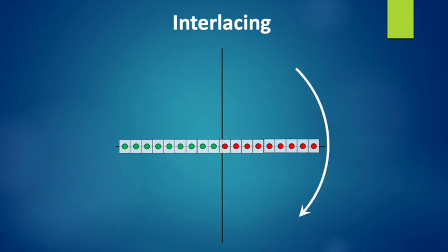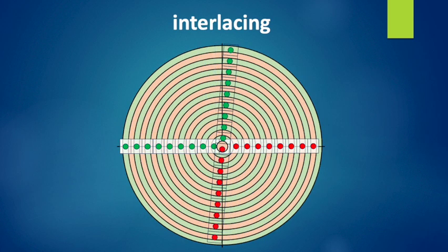If the LED row is now rotated by 180 degrees, the LEDs are shifted by half the LED spacing. In this way, the resolution is doubled. At the same time, the image is now updated twice per revolution, although not in full resolution. This increases the frame rate and reduces flickering.